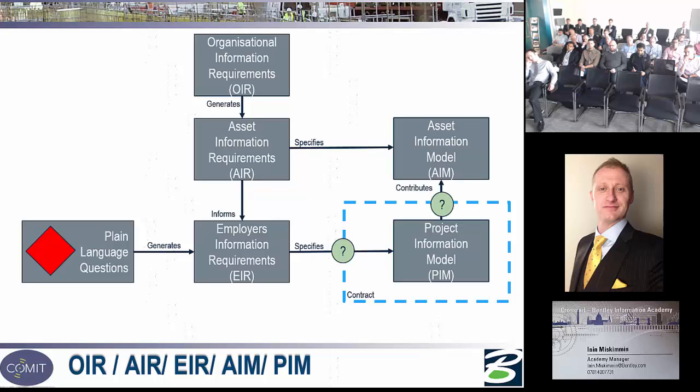So if I've got a filter in the ceiling that I need to change, the information in here needs to tell me where to isolate that filter before I change it. Where do I go to get that bit of kit to change that filter? How often should I check it, etc. So it's all that information that I need within a dictionary. And I'll come to that a little bit later on because there's a problem here, a big problem.